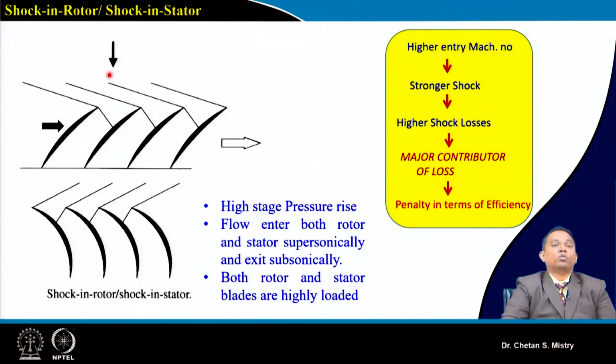In line with what we said, when we are expecting our pressure rise to be large, and higher performance from our compressor, then this kind of configuration is used. So here we have our shock standing at the entry of my rotor. Similarly, at the exit of the rotor, we will have higher absolute velocity, and that will lead to supersonic flow at the entry of the stator. Here the rotor and stator are both highly loaded.